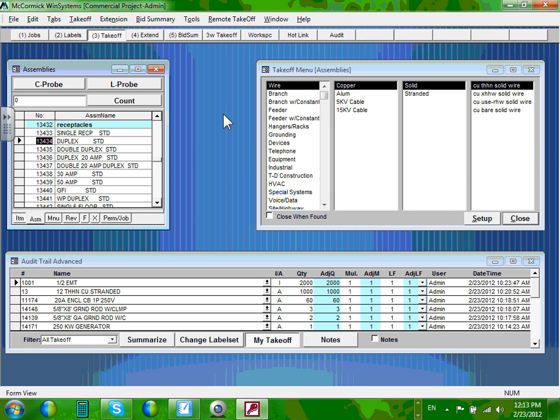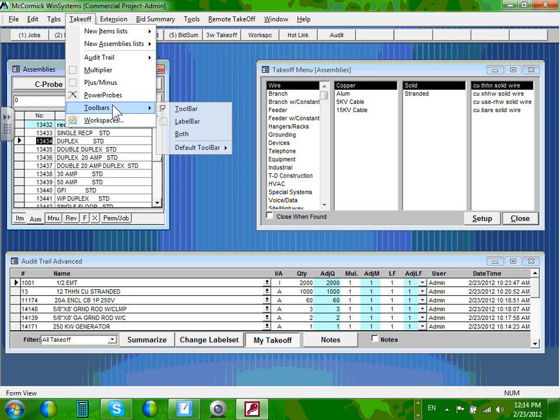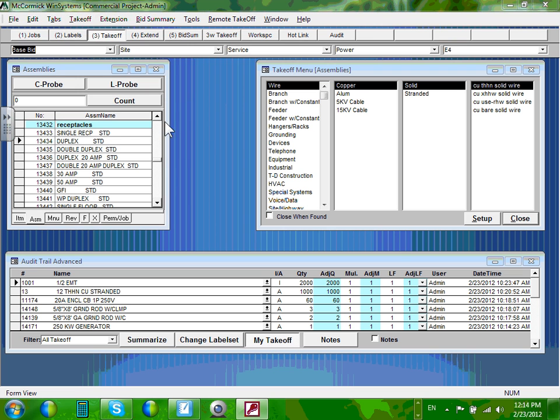How am I going to do a takeoff? Which label am I taking off under? It's been a common mistake for the last nine years. No problem. Go to the toolbar and make sure you click that label and your label is back. Okay? I can help you with it if you wish. That's a common mistake that people have.